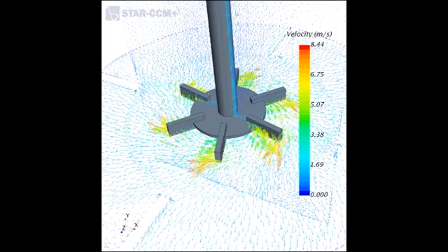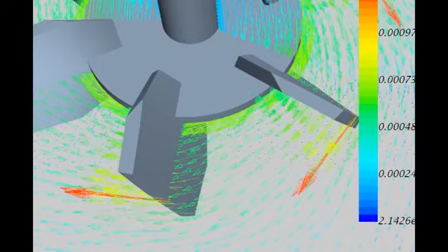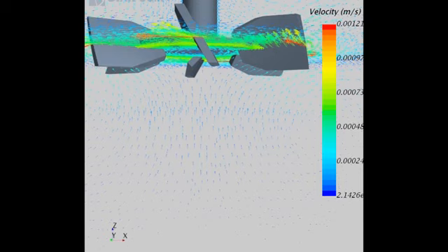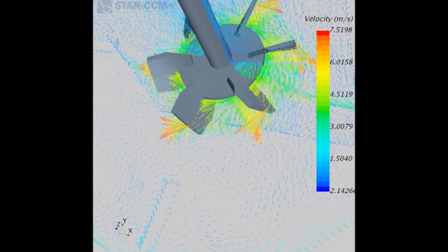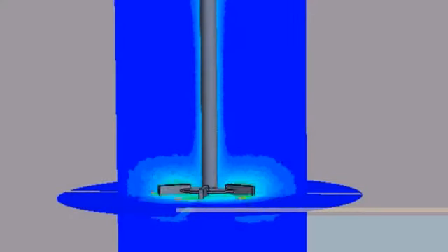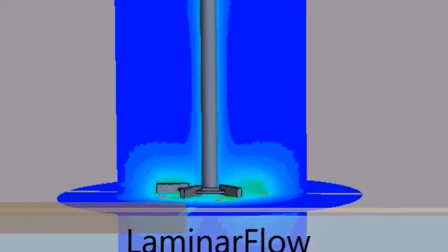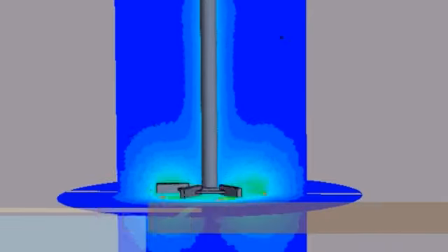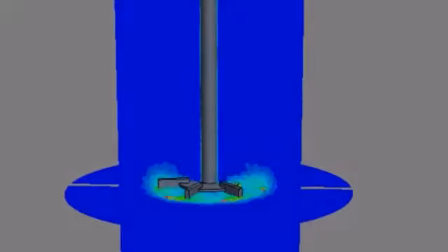These are the velocity profiles of the simulations. It can be seen that around the impellers, the velocity is radial. This is because as the impeller rotates, it imparts momentum and energy to the fluid, and so the fluid moves, and this is what we see in the form of velocity. Over here we can see some circular behavior, and this is because of the friction of the walls, and because the impeller is sending the fluid upwards.